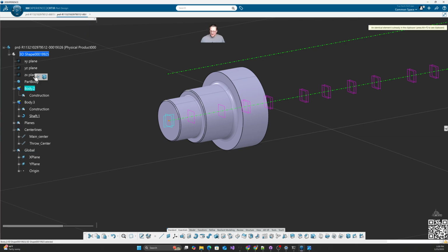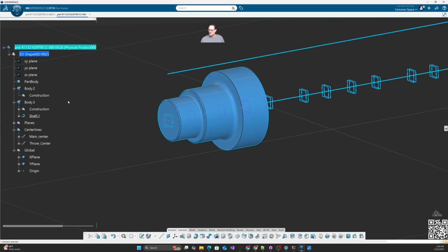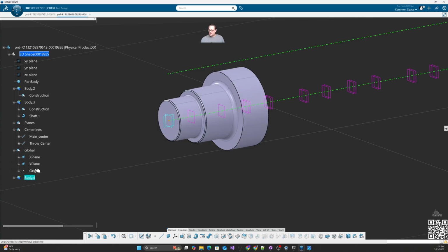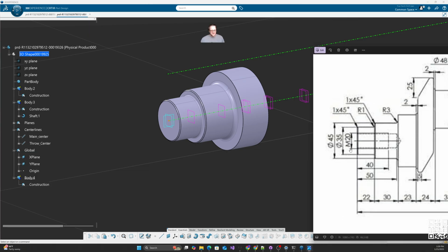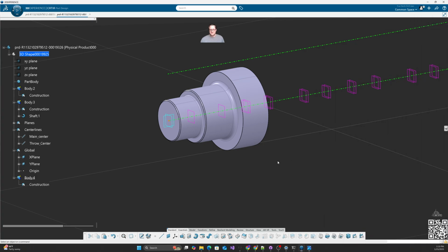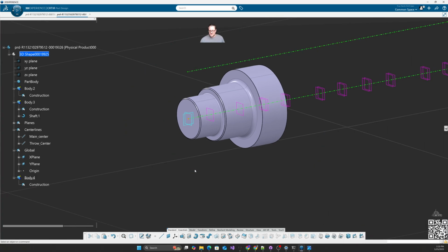Let's copy this body again, and we'll paste that in. And let's focus on the hole. So the hole is an M20. The threads are 40 deep. The hole to the start of the bottom angle is 50. So an M20 should be about a 17.5 millimeter drilled hole and then tapped out to M20. So let's do that first.